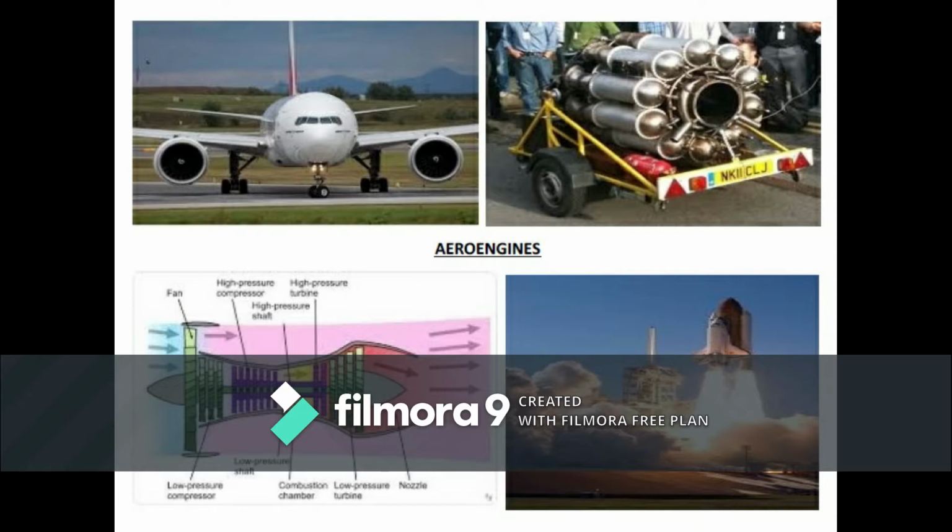So the turbojet engine will consist of an air intake through which the air will enter the engine. After that there will be a compressor. A compressor will have a series of blades, which are further grouped as rotor blades and stator blades. The air entering through the air intake will pass through the compressor. As the name says, the compressor will compress it and increase the pressure.